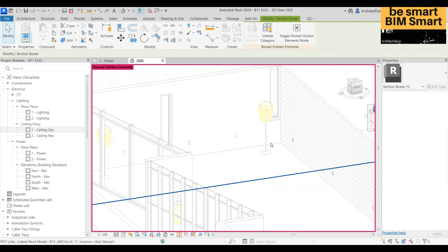What we model usually is conduits. We want to show where the conduit would run because this is helpful. In the actual construction, we are putting the conduit first. We don't put the wire, right? We put the pipe, the conduit, and then we put a string right there, which will be the reference. And then later on, the electrical guys will put on the cable and pull the cable and finish it, right?